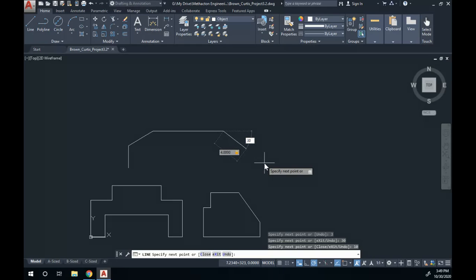If you look at the textbook, the angle that it gives you is the angle with respect to the different angle there. So if you look at the way AutoCAD is projecting its angle, and you look at the way the textbook is projecting its angle, based off the rules of geometry, the opposite interior angle for parallel lines. If I have a bisecting line that crosses 2 parallel lines, opposite interior angles will have the same value. So looking at the book's picture of the angle with respect to the picture that's shown in AutoCAD, as long as those 2 angles are the same, it'll give you the same angle. So 30 is what I want.